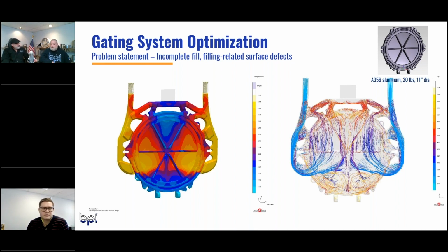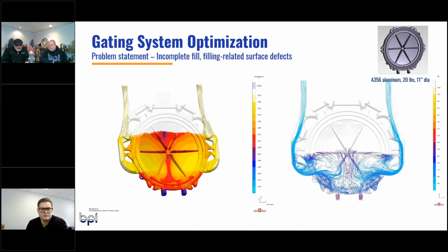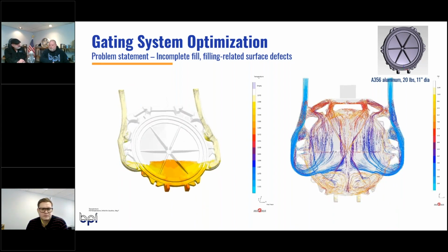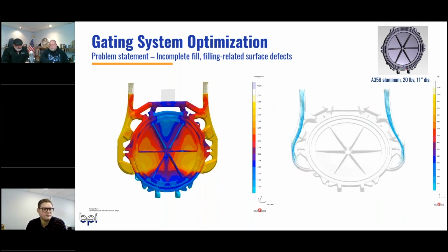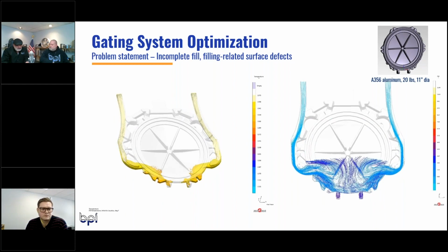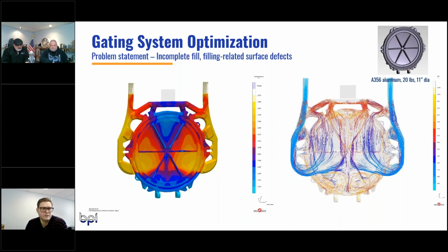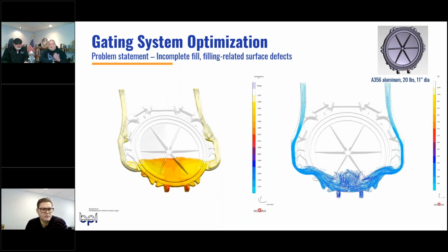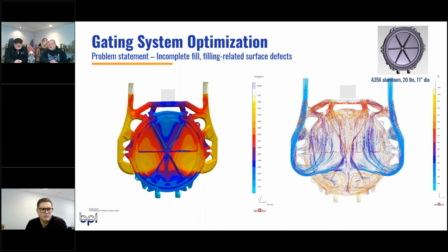Dimensional accuracy, of course, the part's going to shrink. So there's a rule of thumb, 7 thousandths per inch type of rule that we typically try to build into that. On the surface finish, I think that's all kind of comparative. It can have to do with the turbulence for sure, but it's all kind of comparative to the mold itself, the structure that's around the part that you're trying to pour. So there are different types of coatings, different types of sands, and different uses for these coatings that create different types of surface finish. So I wouldn't see this as being a means of predicting surface finish for sure, but you could get into the means of predicting the possible dimensionals. All right, thank you.